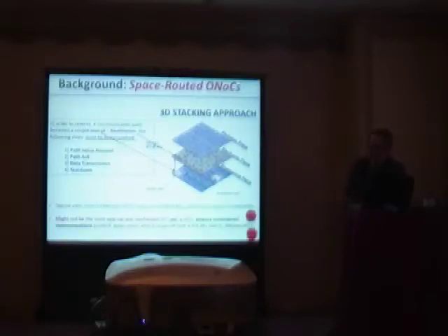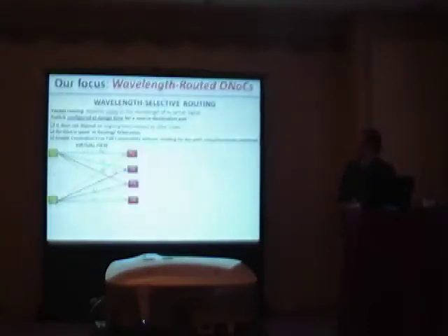Unfortunately, here the optical path control is really expensive due to the high NoC topology, path setup latency, and also contention. In fact, this kind of mechanism is really inappropriate for cost- and latency-constrained communications. Our work instead is focused on wavelength-routed optical networks on chip.